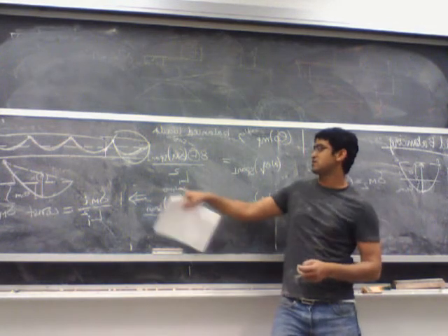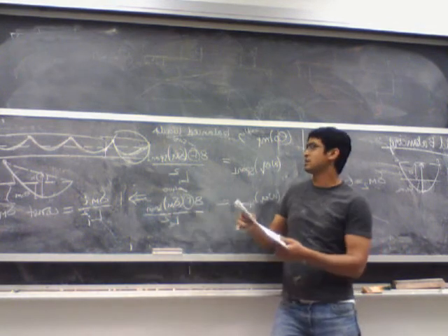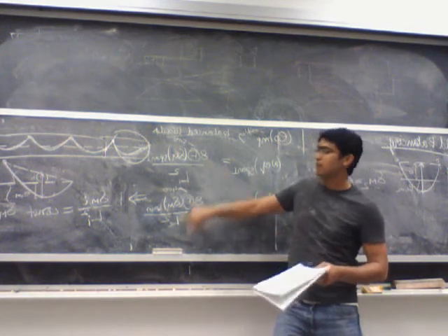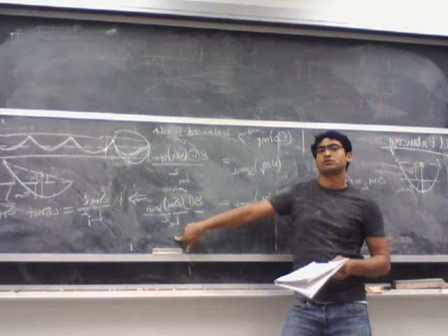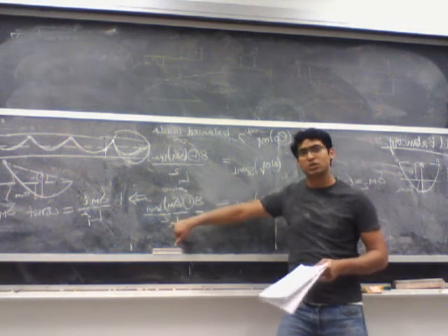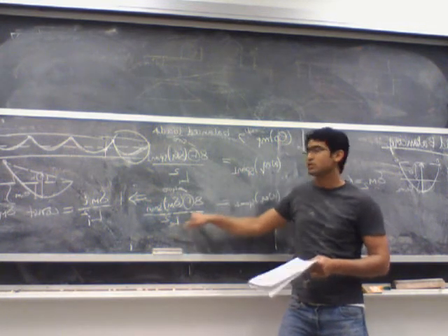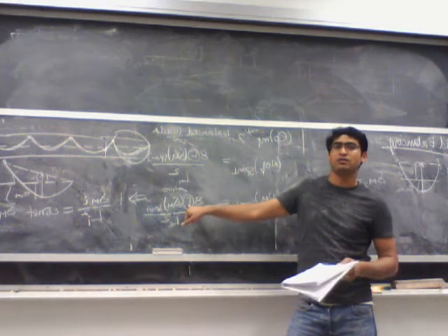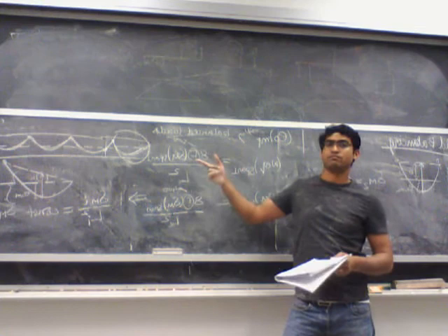But let's say if this is 60 and this is 50, right? Then you cannot directly equate these two because omega equivalent is dependent on L1 and L2 also. So what I'm saying is maximize both of them. Use this formula to find out F from the first span, F from the second span, and pick the larger one.